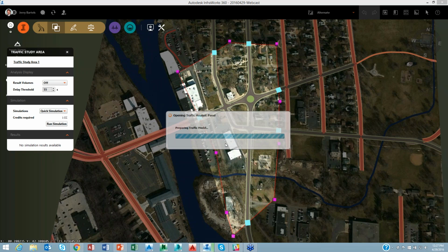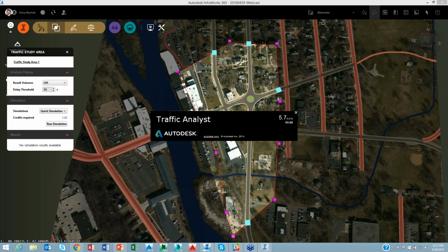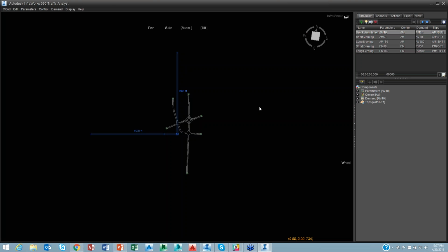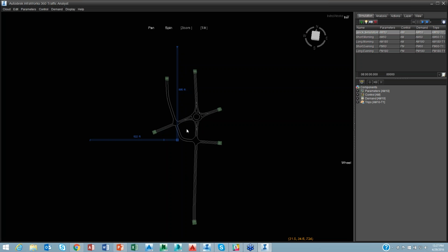Now in doing so, we should see that there are a couple more intersections that are created. Basically those intersections will be the entering into and out of the roundabout. Those two should automatically be populated, so we shouldn't have to go in and configure those. That should happen for us automatically.